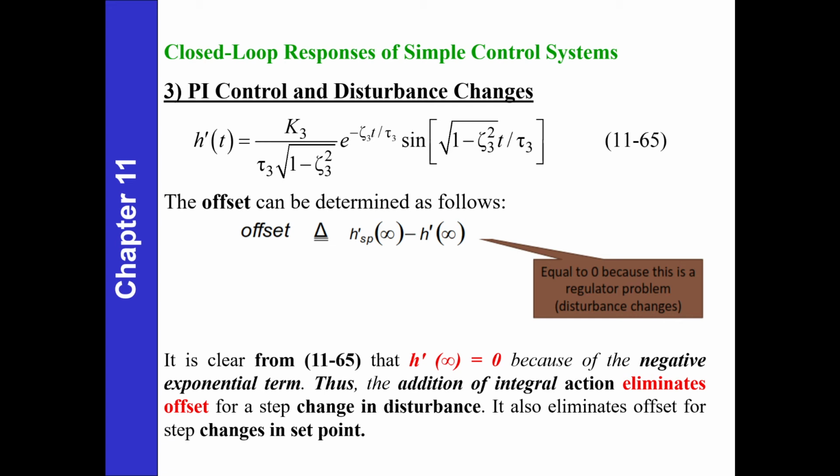But for this PI mode, there is no offset because with PI, the integral will eliminate the offset. Okay, this is mathematically showing you that there is no offset.